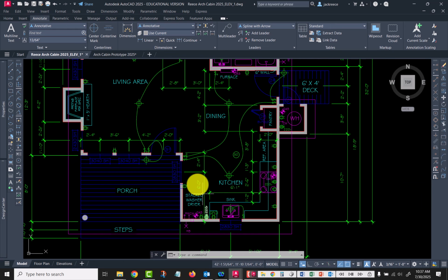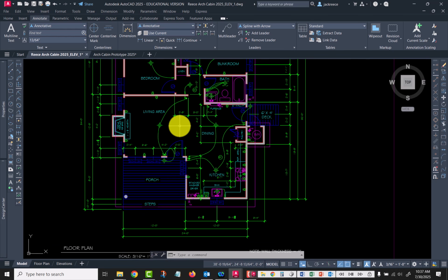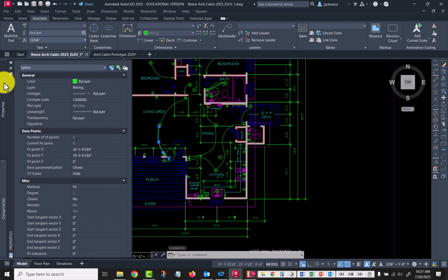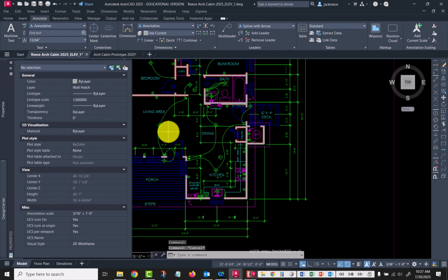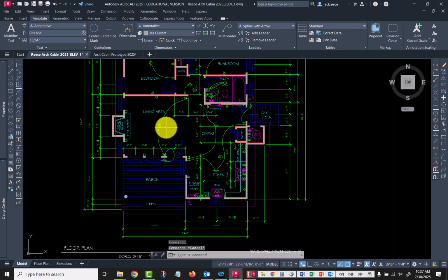So that's that. So this is the drawing. One thing, it said to set the line type when you draw the wiring. It said to reset the line type. I found you don't need to do that, because you really don't want them to show up as dashes here in model space, because that throws it off over in paper space. So none of the dash lines are showing up as dashes here in model space, and that's okay.